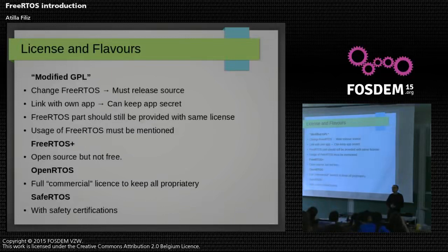And I'm familiar with a few commercial tools from Atmel: if you use their official development tools, they have a tracing utility where you can log events into the RAM and download them via serial debug wire or JTAG.